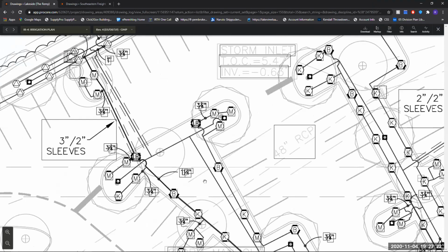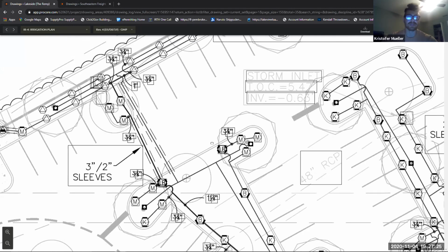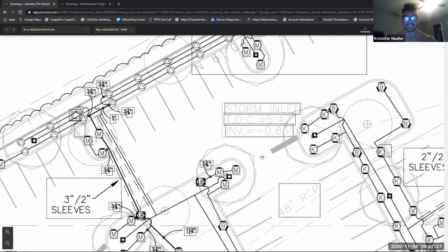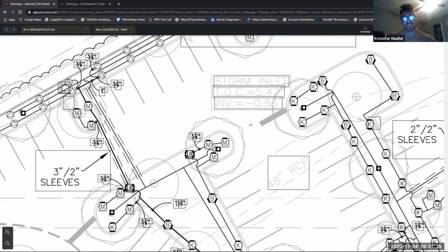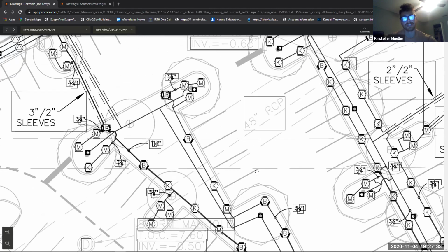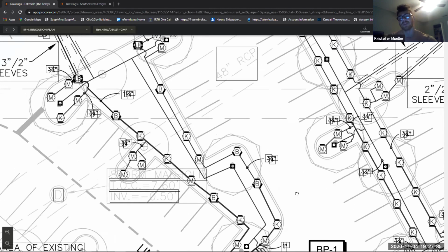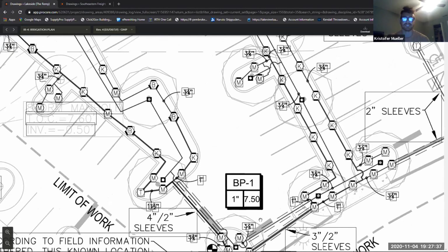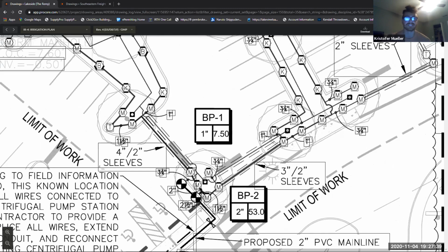Rule of thumb is a 3/4 inch pipe should have 2 to 3 heads on it, and an inch can have 5 plus whatever's on the 3/4, and then you go adding on to that. So that's how you'll determine the size of your valve and stuff.